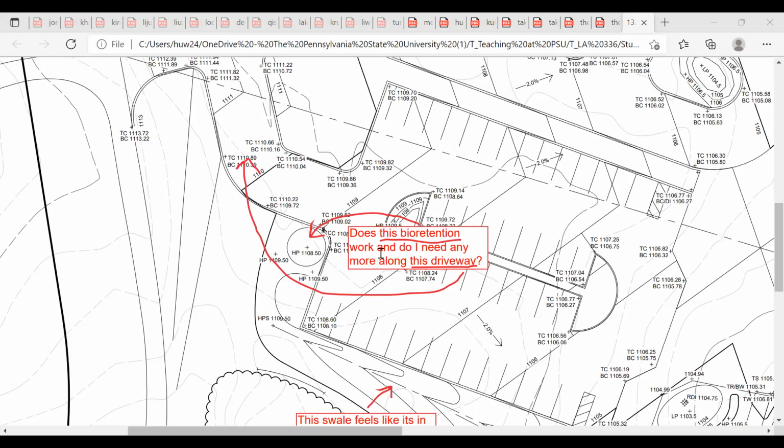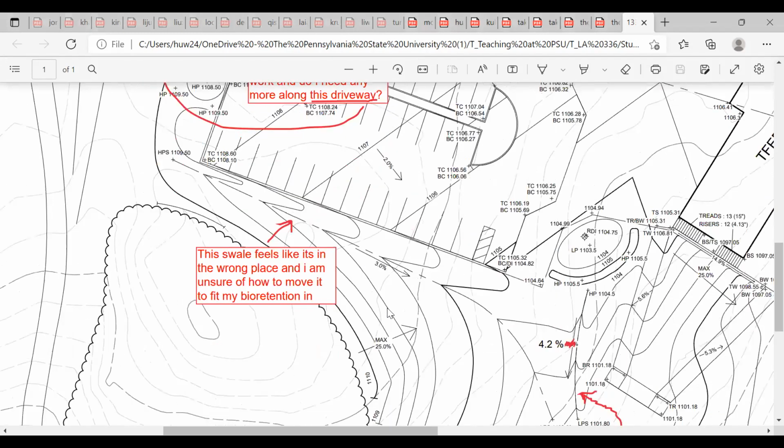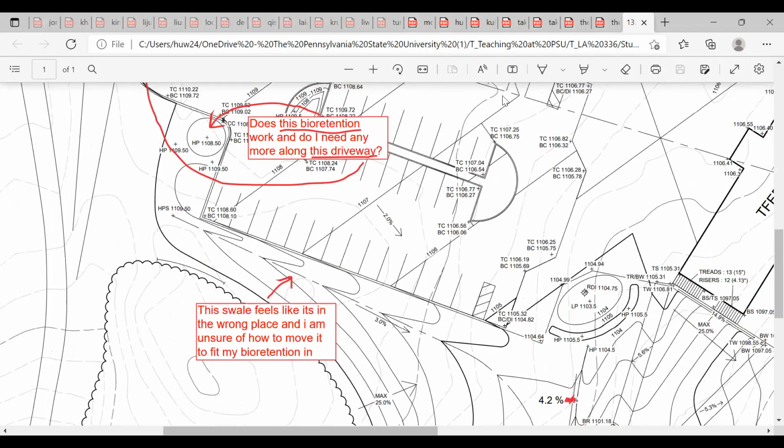Well, we still need all kinds of different elevations here. 1109.2 LP, that's a half foot deep cell, so you would have a 1109 contour. So the contour looks okay. Just need to label it. Label the contour, HP change to LP. Then that should work.